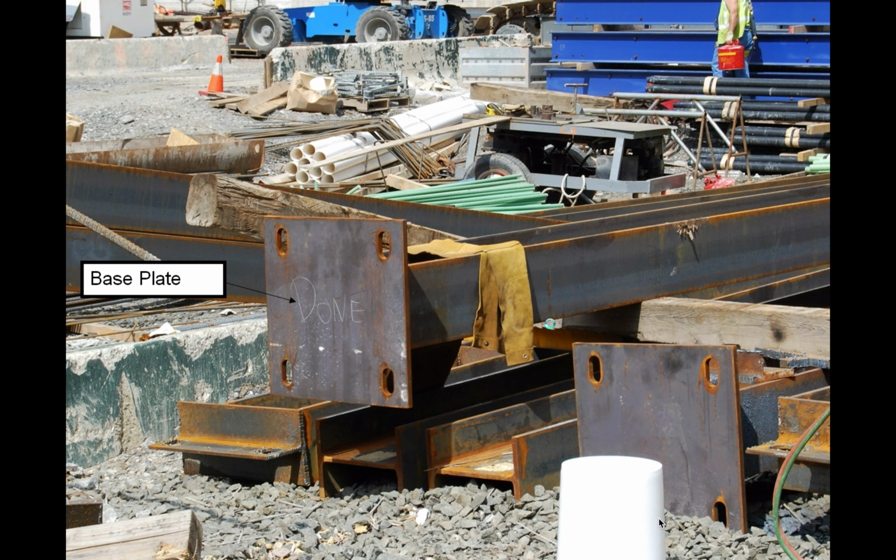And the reason why they're drilled like that is it's easier to align and to get in place and to shift where you need it. It doesn't have to be as exact as if it was a round hole when you're making the steel connections between beams later on. So you get those aligned over the four connections, align it, get it to where it needs to be, verify with survey, and then you bolt them down.